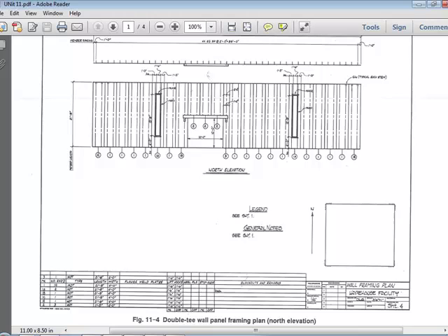It has typical abbreviations on page 149, legend information. Then on page 150, it gives you the steps for drawing framing plans, starting with the column and then the beam on the next page. And this has to do with your assignment. I want you to follow these steps exactly in the assignment.